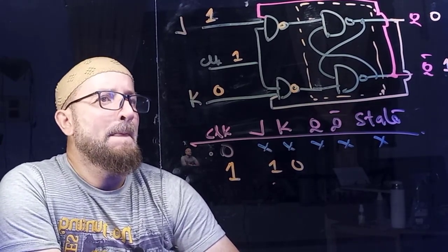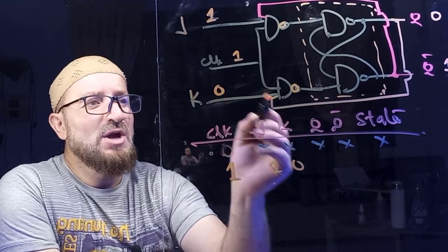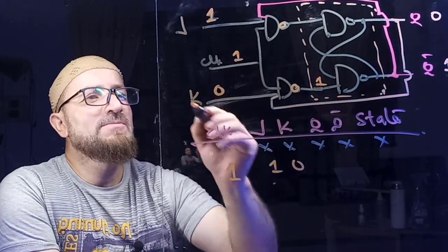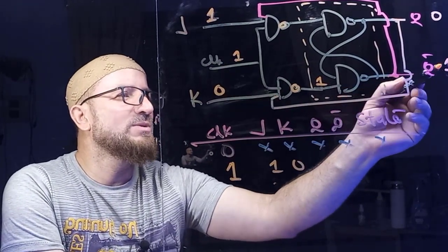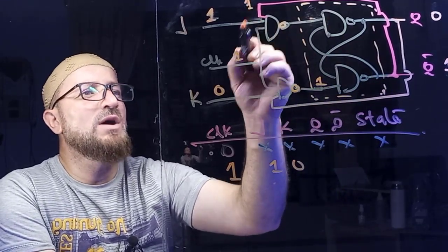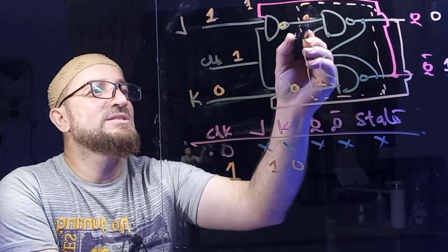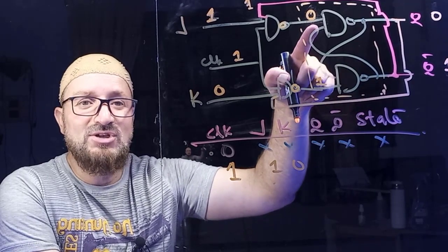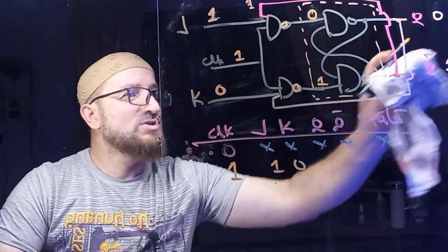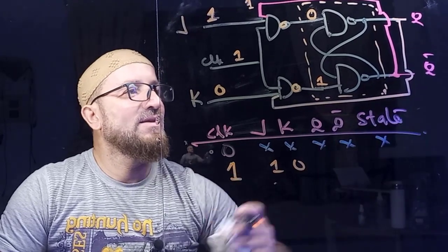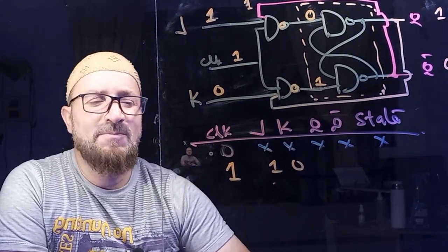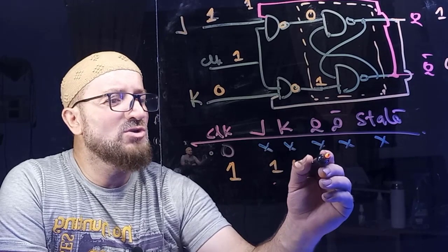Let us see. Now, this is 0. So, immaterial what the other inputs are, this is going to output 1. Right? Now, what about this guy? This is 1, this is 1. What's coming from this side? The 1 is coming from this side because this is 1, reset state. Q complement is 1. So 1 is coming to this gate, okay. Now all the 3 are 1, 1, 1. What is going to be the NAND output? It's going to be 0. And we know the latch, if the 1 is on the bottom, it's going to set, okay. So that means it was reset, now it will set. So it will become 1, 0. So that means whether it was set or reset previously, if we are putting J1, K0, it is gonna set.